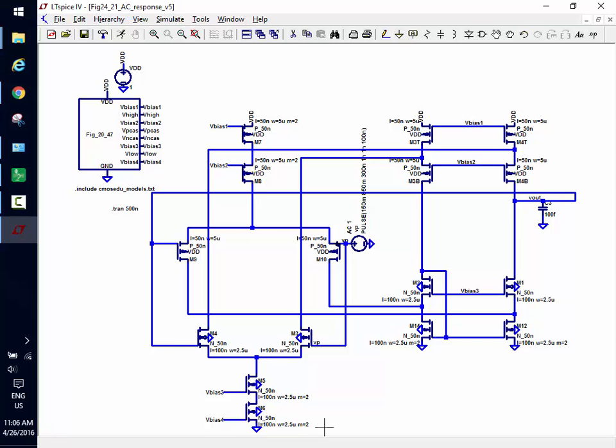If I do that, what happens when, say, the NMOS diff amp shuts off? Then it would force twice as much current through each side, right? But I've got a diode connected device here. It'll just adjust to sink that extra current. So I'm going to get a different gain depending on the input common mode range.